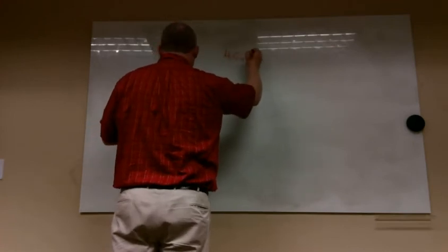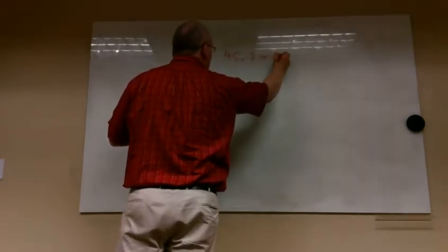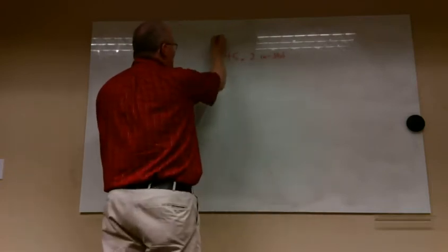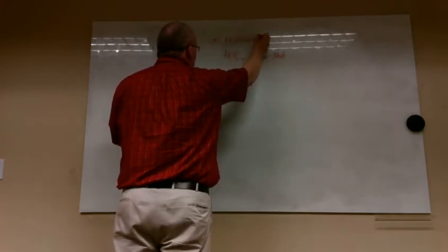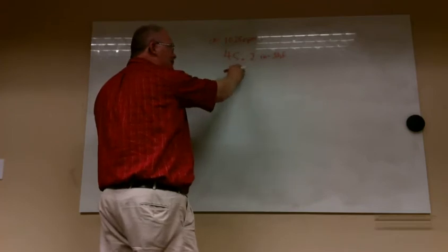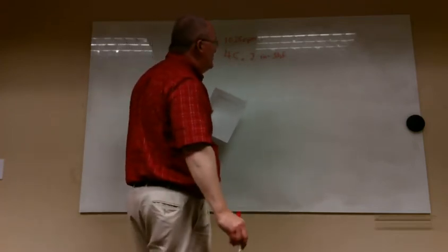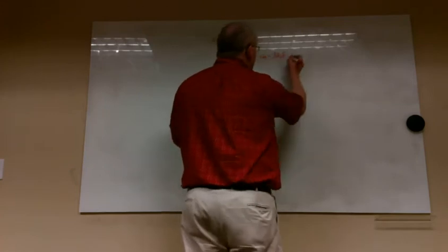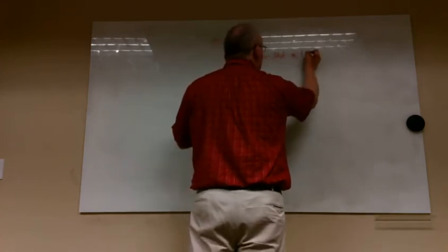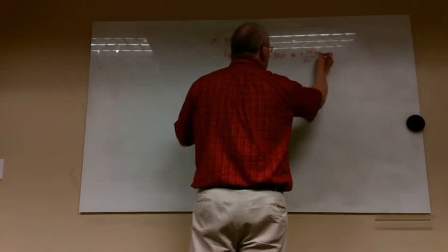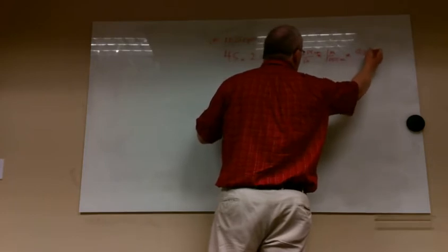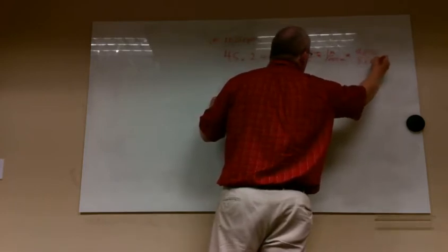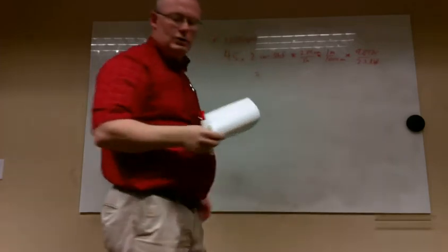45.2, and that's at 1035 RPM. You get this, not stall, it's at 1035 RPM, you get 45.2 inch-pounds force. So you multiply that one times, once again, 2.54 centimeters to the inch times 1 meter per 100 centimeters times 9.81 newtons per 2.2 pounds force, and that will give you the torque in Newton meters. Okay.